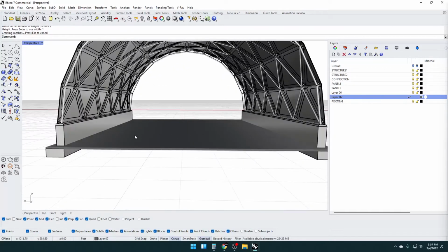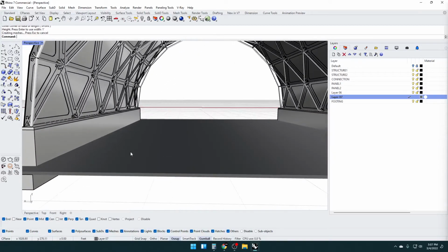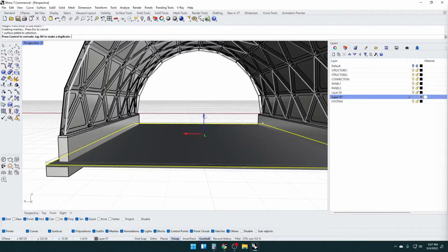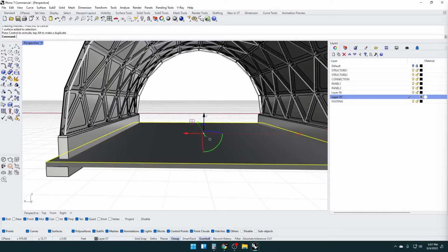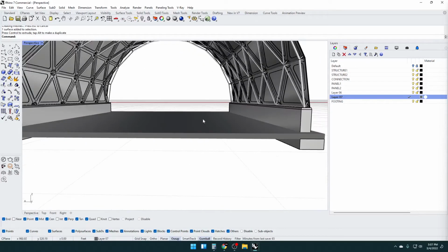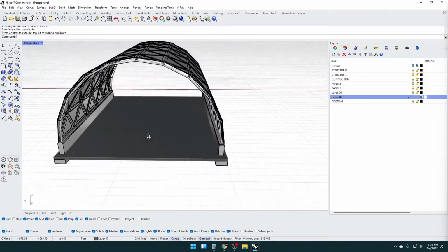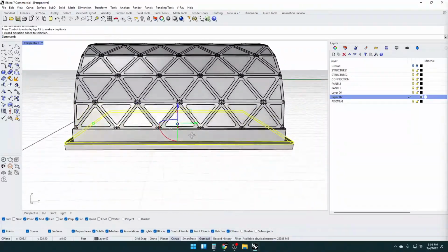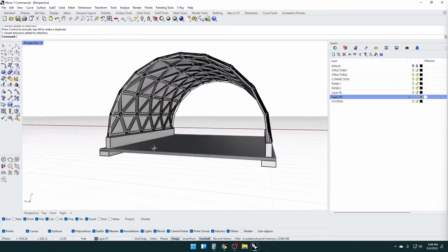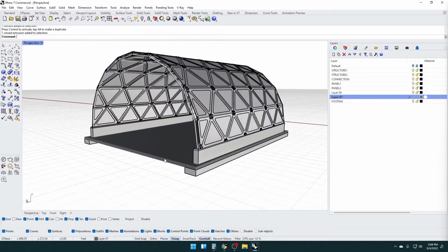from the ground there. So that looks a little bit small, but in reality, let's say if this was an outdoor design, the slab would be poured on top, something like this, and there would be sand and gravel down here, compacted. So that kind of covers, for the most part, some of the detailing in here.